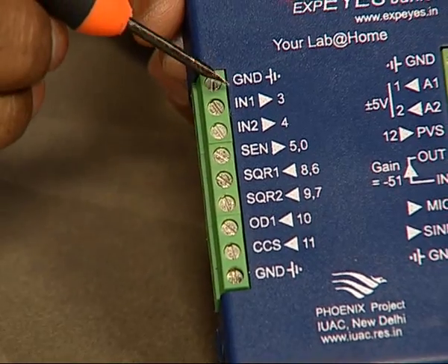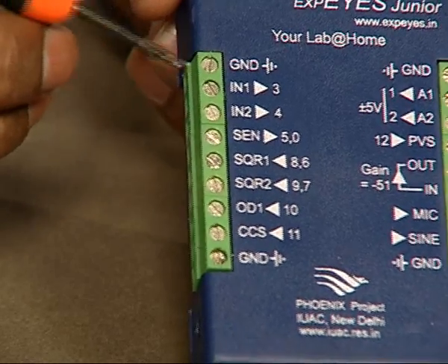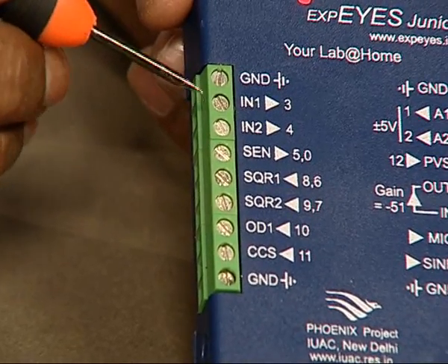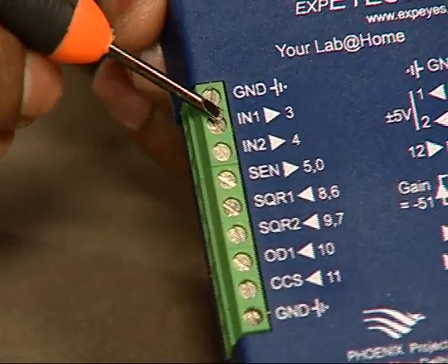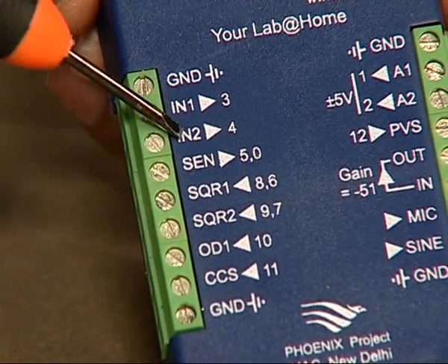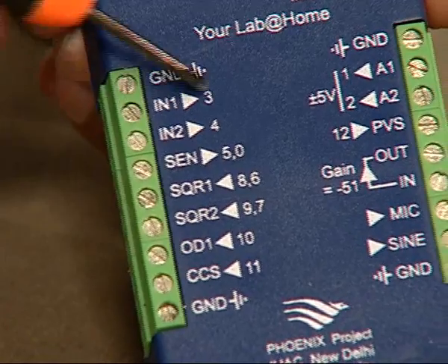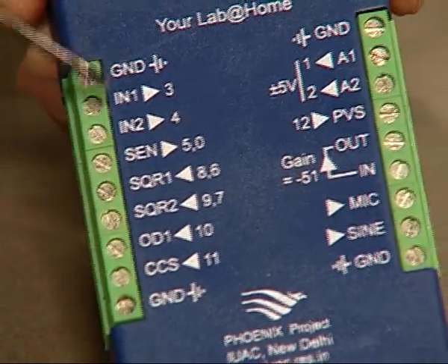They are also measurement terminals, but they can take a voltage in the range of 0 to 5 volts, but they have some additional features, like IN1 is capable of measuring capacitance, and also IN1 and IN2 can measure digital signals, like as applied voltages, the logic state can be measured.